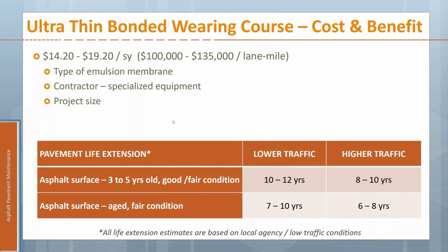Overall, your cost per mile will be more. So one of the strategies would be to, maybe if you want to try this, get a selection of locations. Maybe it's a mile here, half a mile there, maybe it's a neighborhood, but try to group some projects so that you're paying for one mobilization cost, but getting a lot more area of pavement down on the ground.